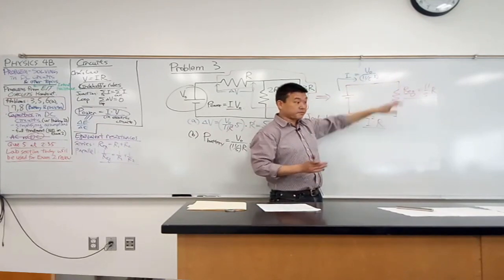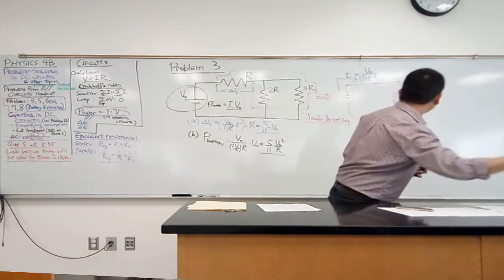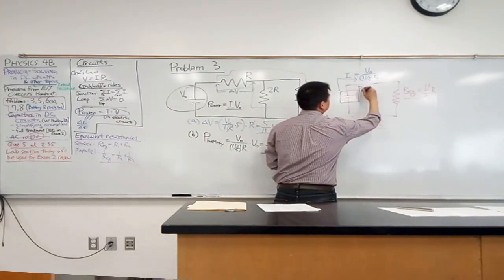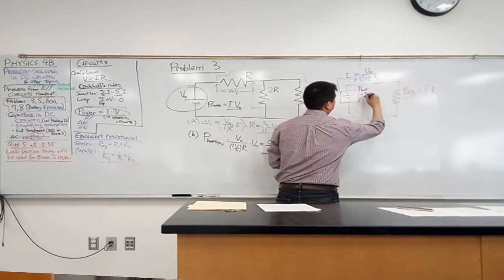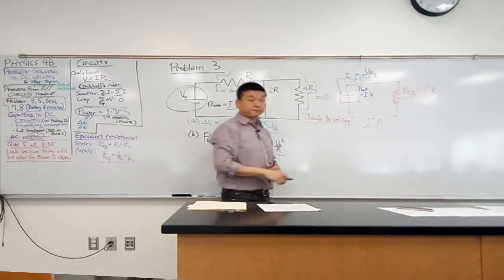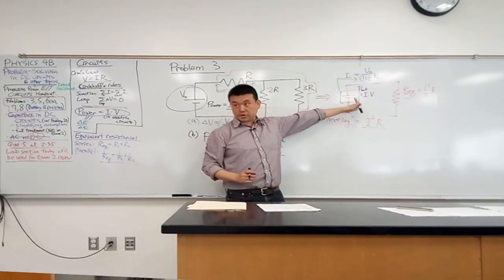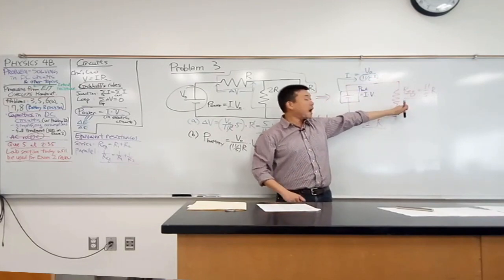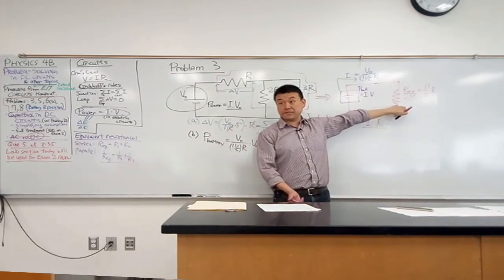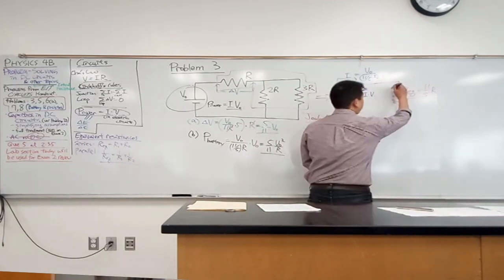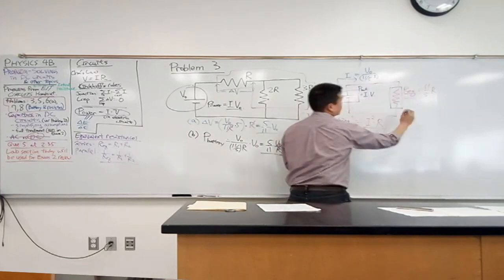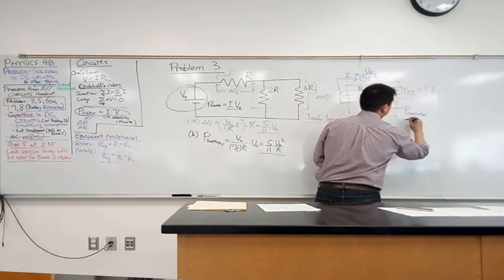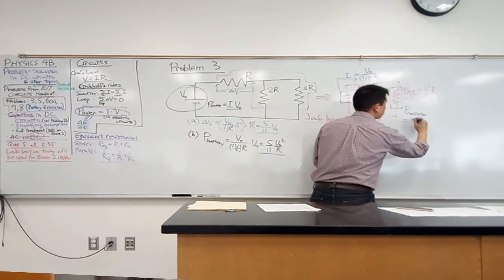yes, we're looking at this simple circuit, then what we can say is, all right, the power output of this battery would be current times the voltage. Well, for this very simple circuit, whatever the power output of the battery is, that should be the power dissipated by this single resistor, right? So this should be the same thing as this. Power dissipation by the resistor will be equal to current times voltage.